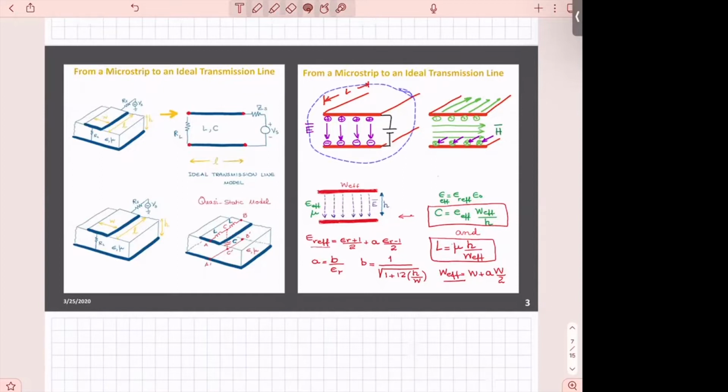And for this structure that we have simplified, we now can find the capacitance and the inductance, but because the structure has a length, we define those per unit length. So we take a particular length. You can take a length L, find a total inductance, a total capacitance, but to find the per unit length, you will have to divide both the capacitance and the inductance by this dimension. As a matter of fact, we use length here, and then I will write it so you don't mix it up with the inductance. So practically this is length.